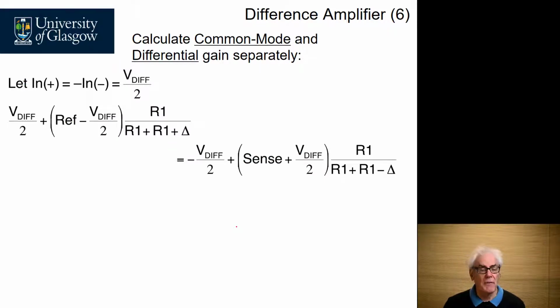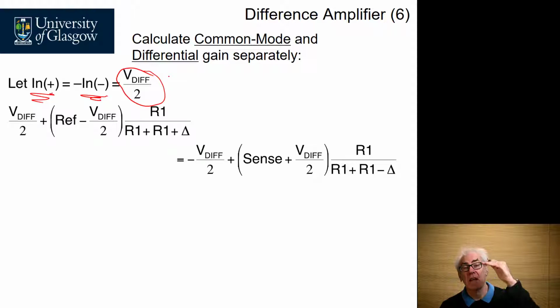In the case of the differential one, let In plus equal the negative of In minus, and we'll call this difference voltage VDiff divided by 2. In other words, the full input voltage is VDiff, but In plus is going positive and In minus is going negative. Doing the analysis in the same fashion as before, we land up with the two equations here.